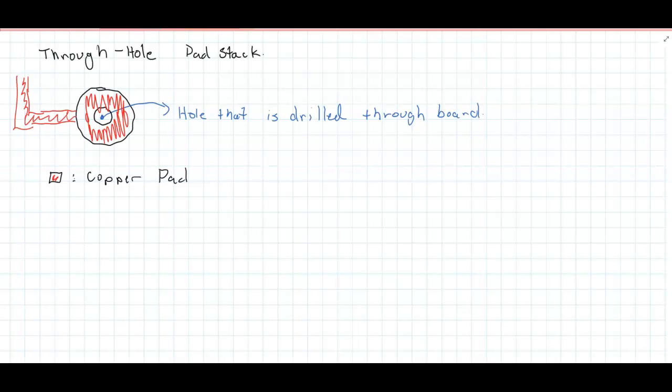But the standard for this, if we do the pad size, well, level A, this is my minimum hole size D plus 0.1 millimeters plus 0.60 millimeters.